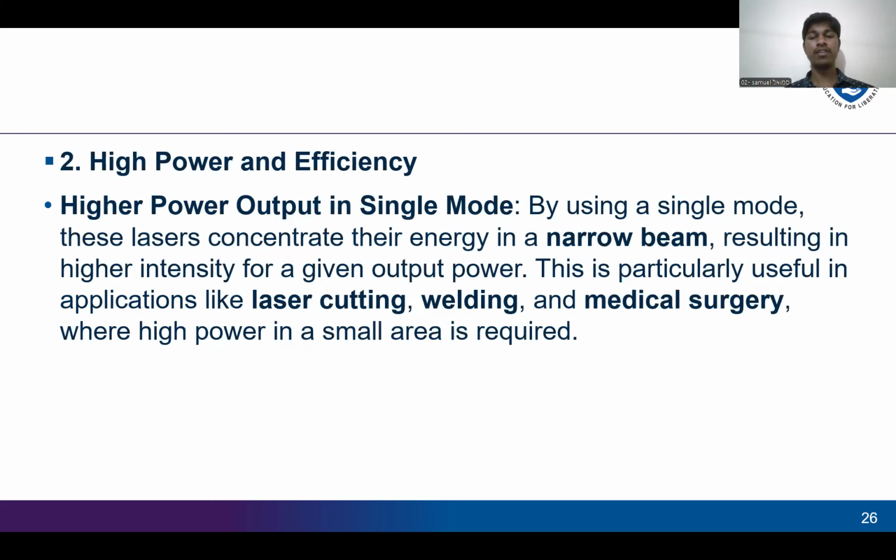High power and efficiency. High power output in a single mode. By using a single mode, these lasers concentrate the energy in a narrow beam, resulting in higher intensity for a given output power. This is particularly useful in applications like laser cutting, welding, and medical surgeries, where high power is needed in a small area.